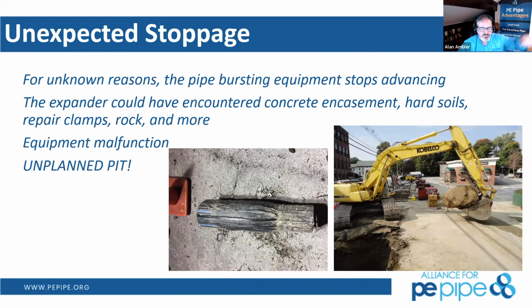We essentially have a pipe bursting machine operator, and then somebody on the opposite side to watch as that pipe advances. So this would not happen. And in that situation, it was rather early in the morning, and the operator wasn't paying as much attention as they potentially could have. But that just became two pits that were dug the next night. They found the equipment, reconnected the pipe bursting process, and started to pull again.